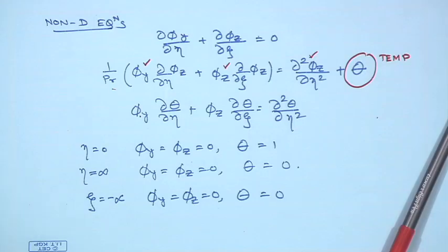So, that is the assumption that we are making. Since free convection flow is characterized by slow upward movement of the fluid, we do not expect the effect of convection to be significant on the final solution of the problem. So, we are not saying it is 0 as in the case of creeping flow, but we are saying its effect is going to be small.